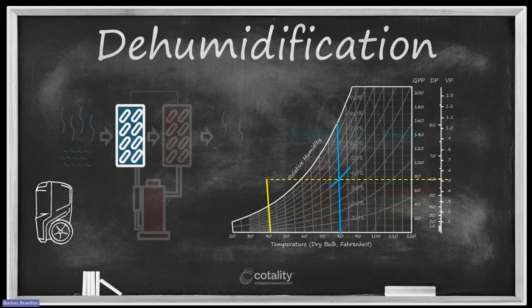What does that mean? That means that if I can cool this air to below 60 degrees Fahrenheit, then I can start to see condensation as a net overall result. I can start condensing the moisture out of that air, and that's essentially what the refrigerant has to do. It has to take that air and cool it to a temperature below its dew point. Not just a little below its dew point, a lot below, so that we can get lots of moisture to sweat out of that air, to condense out of the air.